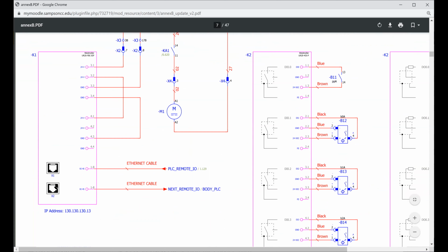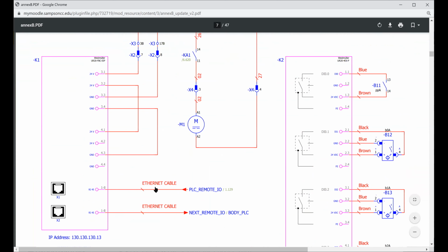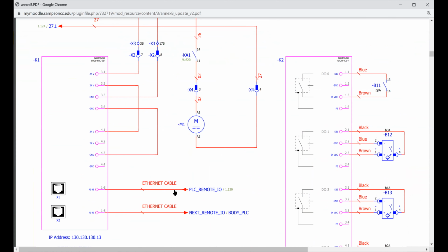You see the Ethernet plugs right there. Those are communication connections, Ethernet cable. So behind these units, up under these, you have something called remote I/O, remote input output. The inputs and outputs related to this limit switch, the one that picks up the over-packs, these sensors, anything back on the back end, all of that is put in through remote I/O.